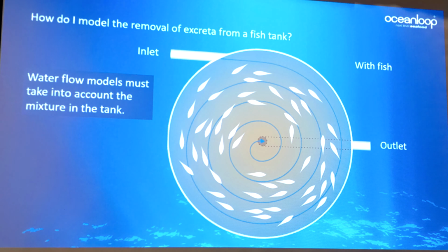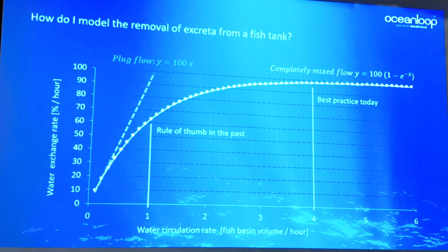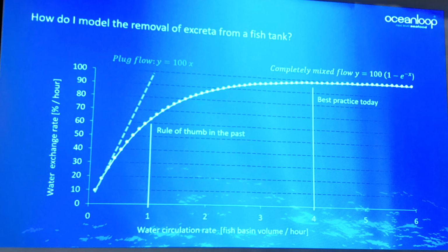And this is really important to know when you go into the mathematical simulations. You see that in this slide pretty well. We have two models. It's a plug flow model, where there is the assumption that there's no mixing in the tank at all. Then you have the completely mixed system, so all the water going into the tank is completely mixed before it goes to the outlet.